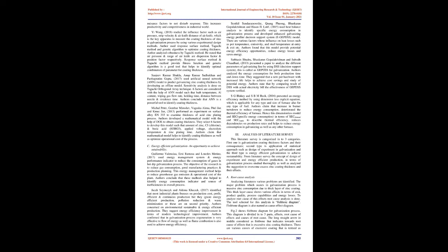B. Design of experiment, DOE, a statistical approach in galvanization process. J. R. Smith and C. Larson, 2019, presented various statistical and experimental design tools such as full and fractional design, response surface method, Taguchi method, central composite design, and different plots like Pareto chart and normal plot. Authors used 2^4 full factorial methods for coating thickness analysis in galvanization and provide comprehensive understanding about different DOE techniques.